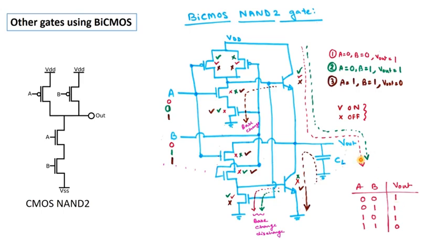Right, now here you see these two transistors are off. As these two transistors are off, you can see this is now open circuit. But what about this transistor? This NMOS is now on. See the red mark? As these are on and this BJT is off, the stored base charge in this BJT can now be removed by this NMOS. Right? Can you follow it?